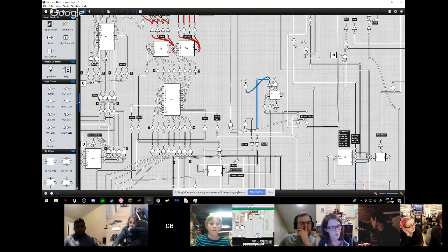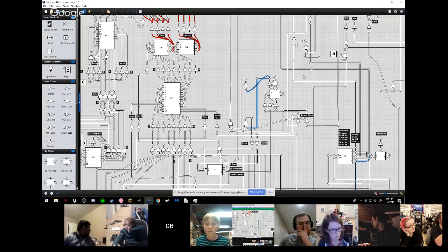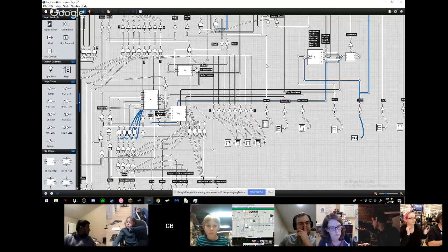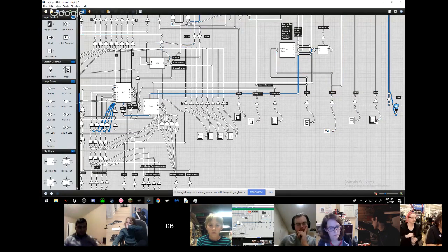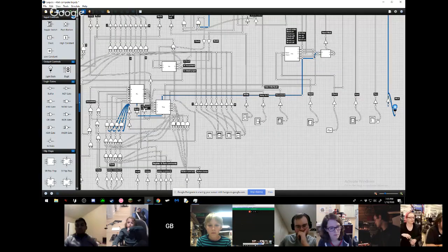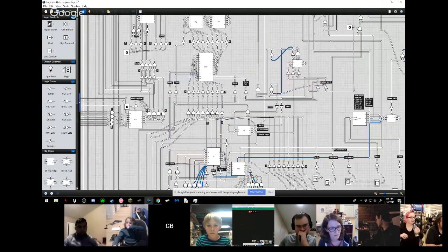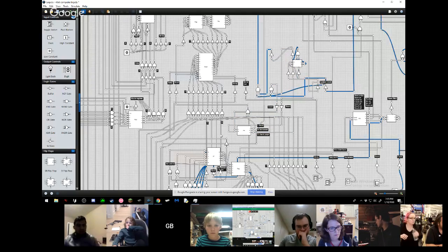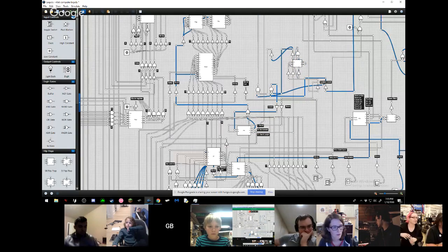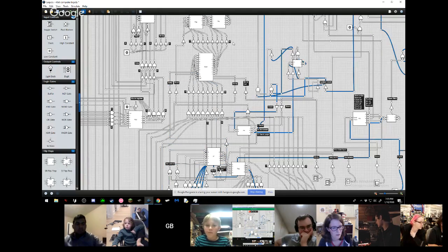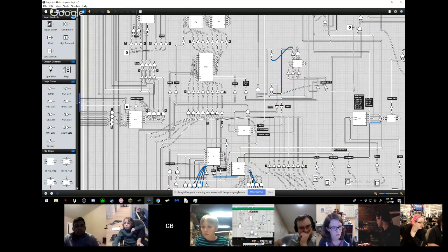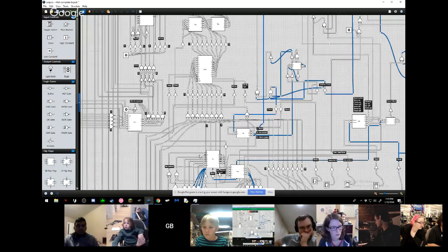You can watch it run. It's not going to be doing nothing. It's reading a command that tells it to do nothing. So let's run it. Hurry up and do nothing. And you see, there it goes. First, it'll increment the program counter, read from RAM, increment it again, and then it'll read from RAM. So then it increments it again, and you could see it doing that up here.